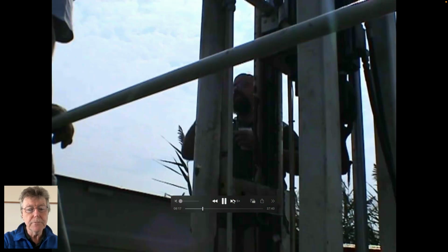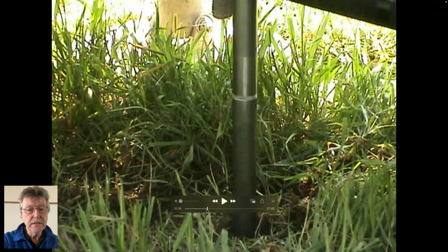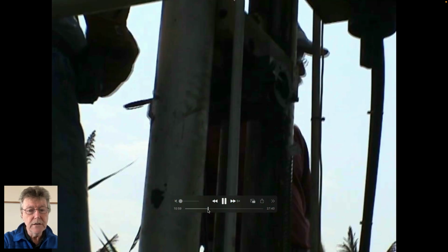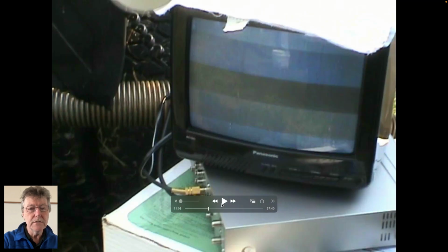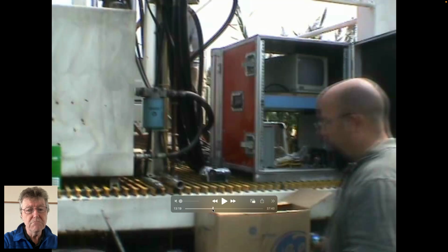This happened to be a so-called VIS CPT, as in VIS, as in visual. And so it's an interesting idea in that as it goes into the ground, it has at the tip a CCD and a sapphire screen like you have on your watch to be able to look out into the soil that you go past. And so it records the grain size and the presence of DNAPLs in the soil as it goes down with depth. And so a bit of an exotic tool, kind of an experimental tool. I don't know whether people use them in practice, but it was using that to be able to do that.